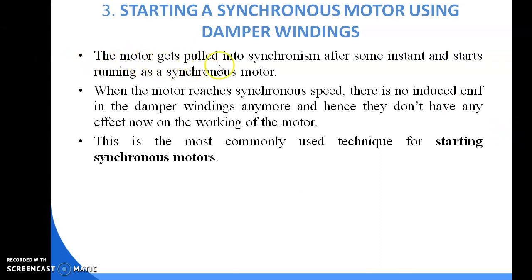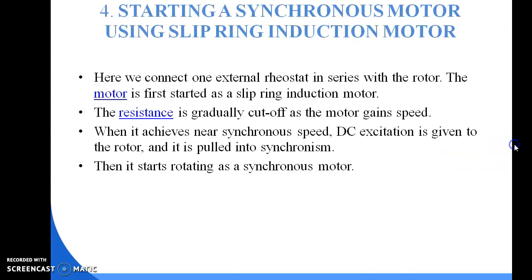The motor gets pulled into synchronism after some instant of time and starts running as a synchronous motor. When the motor reaches synchronous speed, there is no induced EMF in the damper windings anymore, and hence they don't have any effect now on the working of the motor. This is the most commonly used technique for starting synchronous motors.